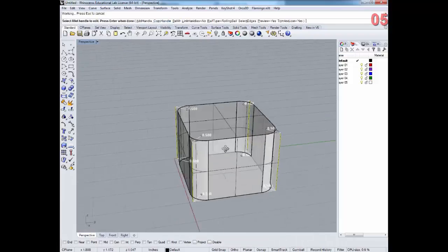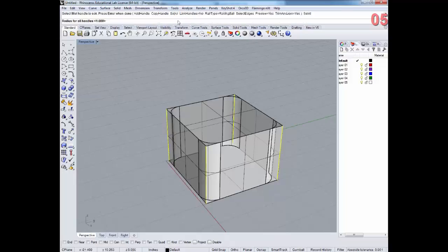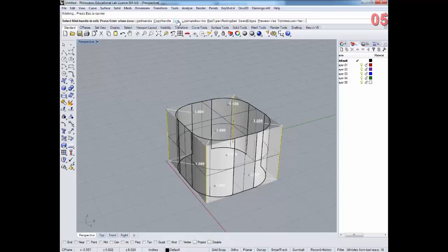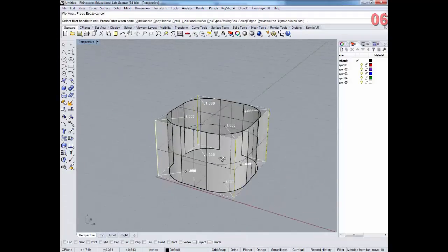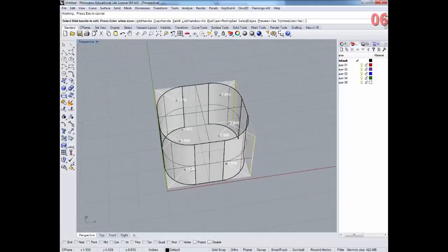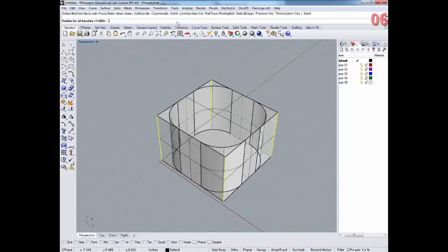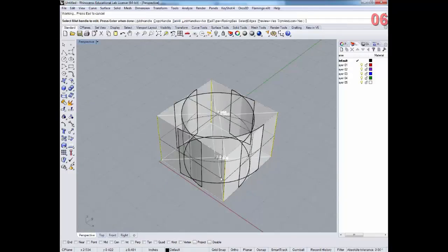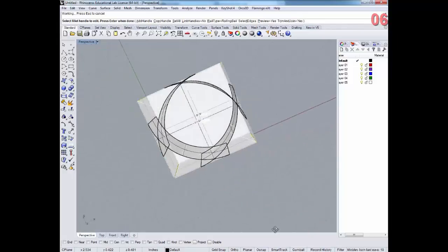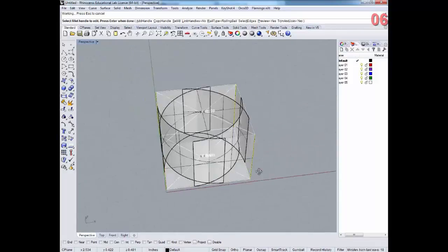Okay, I'm going to hit set all, change that value to 1. And you see that even at 1, the fillets don't collide. Okay, let's push it to the point of failure. I'm going to set all, change those values to 2. And you notice that there, they actually collide. Do you see that? And you don't want to do that.